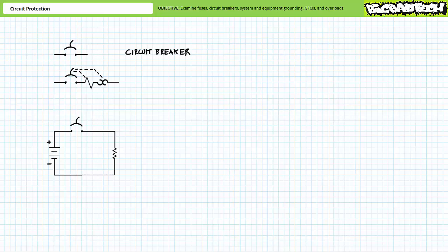A more sophisticated schematic symbol of a circuit breaker illustrates the moving contacts that make and break connection in series with one or more means of detection. The dashed line indicates that when the detection mechanisms detect a high current event, it signals the contacts to open. Additionally, a manually actuated switch allows a user to selectively close and open the circuit breaker just like a switch.